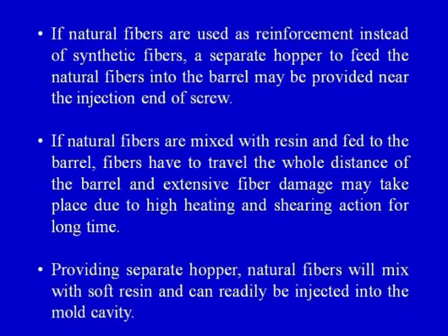Now coming on to a specific case in which natural fibers are being used as the reinforcement materials. On your screen I will read it for you. If natural fibers are used as reinforcement instead of synthetic fibers, a separate hopper to feed the natural fibers into the barrel may be provided near the injection end of the screw.